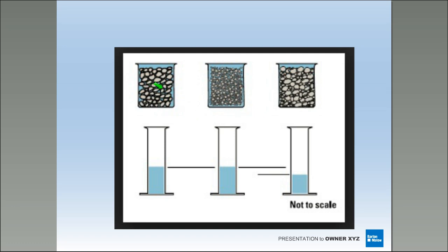If you take a not so well blended, typical 1 stone large aggregate mix, because a large stone's strong and it's got a good strength factor to it, look at the amount of paste I got in there to make that all hold together. If I take a gap graded mix, I got a bunch of voids in here because it's not that well blended. It's not working out for me. Again, same amount of paste. If I have a well blended aggregate mix to fill in all the capillaries and voids, I use less paste, less cement, less sand, less shrinkage, less curl. That's what we're trying to mitigate, is curl and shrinkage.